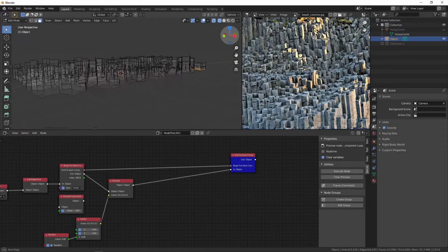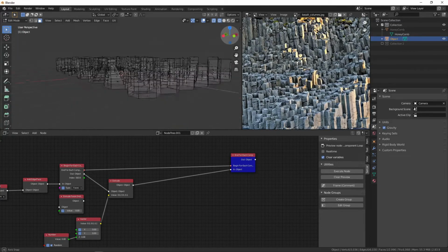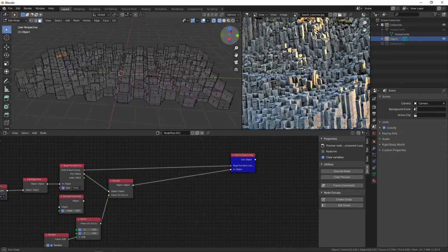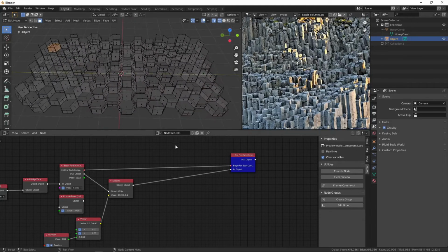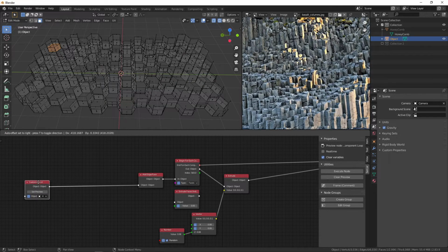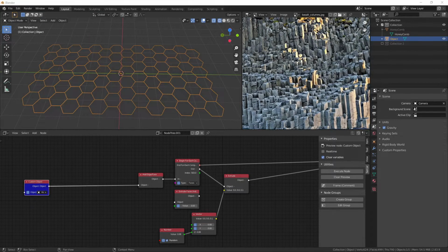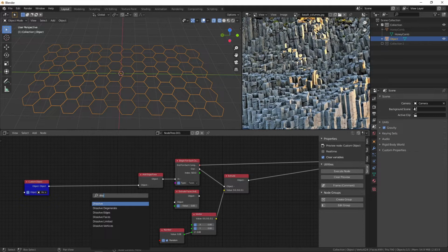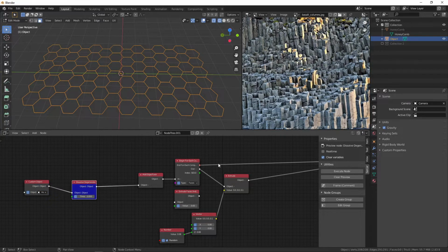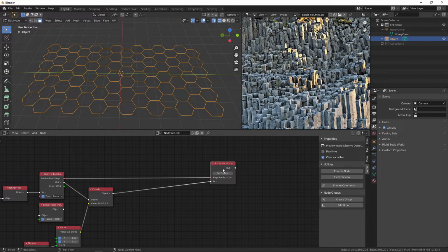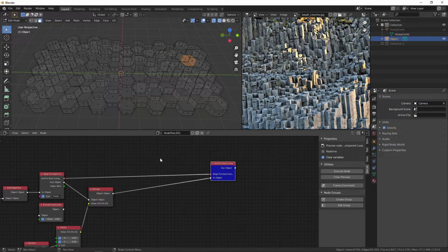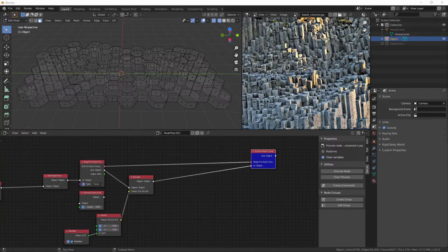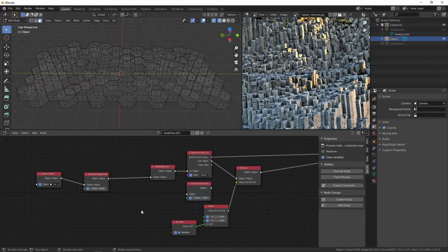See, it looks like we might need to go in the other direction, and there is more geometry there than I thought originally. So let's start back here and delete some of that geometry that it started with. We'll try by dissolving the degenerate components. Try to extrude again. Try a limited planar dissolve as well.